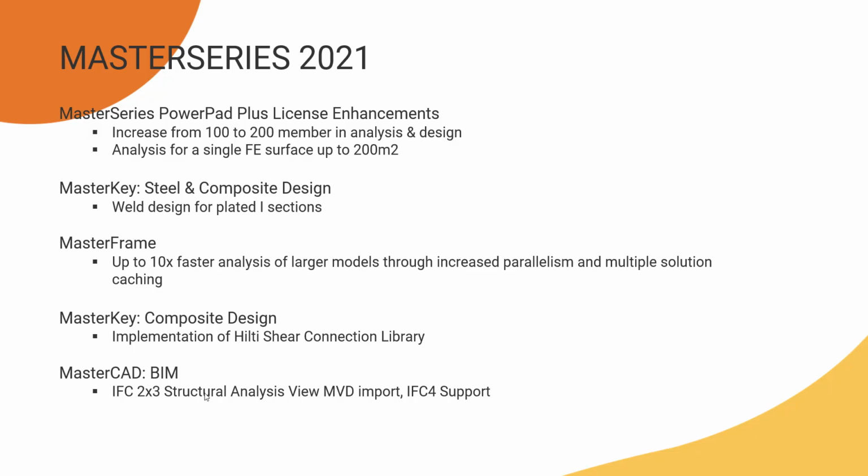So if you have a third-party BIM application that is able to export the structural analysis view, which can sometimes be more favorable, for our purposes at least anyway, than the model coordination view, then we can now import those, and we've seen some examples where that does produce a better outcome for the MasterSeries, which effectively is structural analysis software. Also, IFC4 support is in there as well for this version.